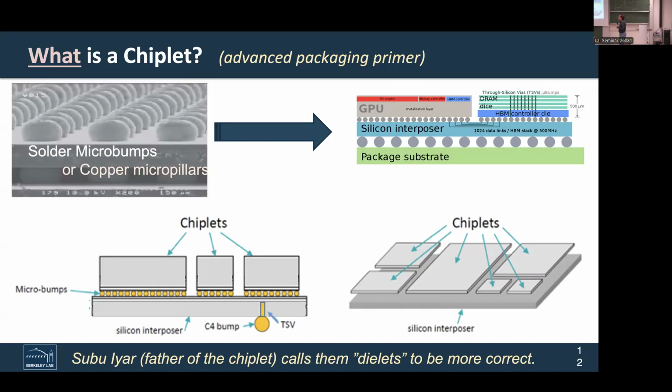They use an older process technology to engineer a lot of little micropins, these little solder microbumps. Now they have hybrid bonding. I'm not going to get into the details of that, but now you have thousands more pins per square millimeter, and they can operate at a slower data rate, but deliver petabytes per second of bandwidth. And then you use an older process technology to put the wires in the substrate here, and you can connect the chiplets together. Now you don't have that PCI bus thing. You've minimized the communication distance, and you have modularity too.